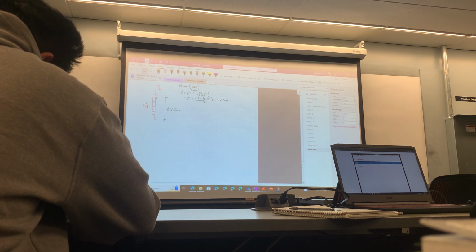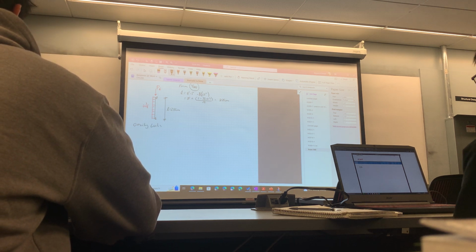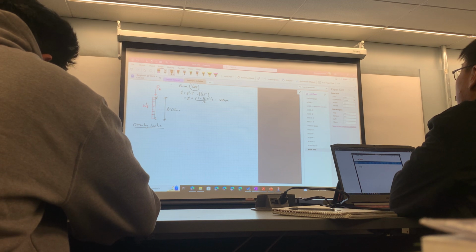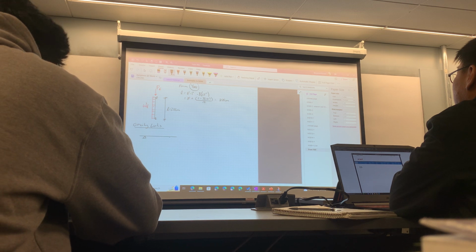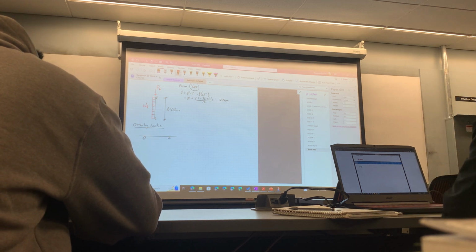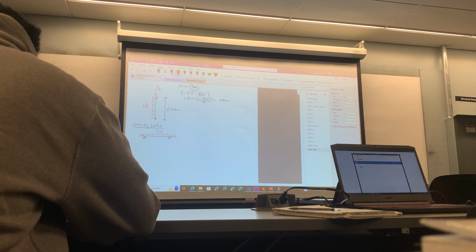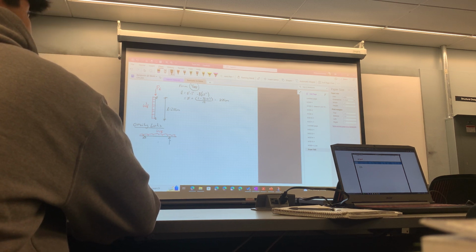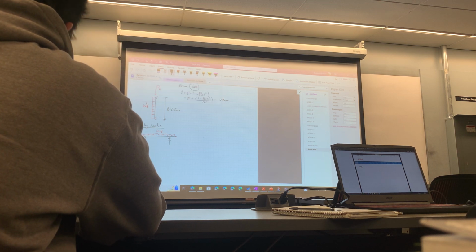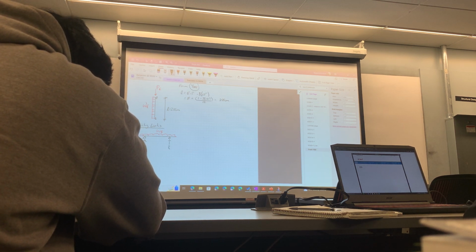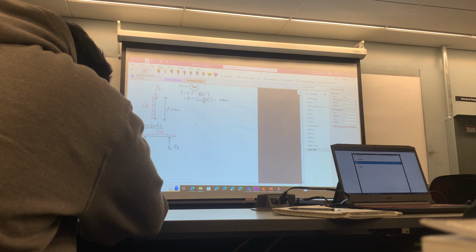Now, when we look at the gravity loads, we're going to have a free body diagram that looks like this. We've got our wall, we've got our other wall, we've got our overhang, here's WF, and then we're going to have our reactions, R1, R2, which is equal to PF. Okay, do you guys see that? That's the roof truss.